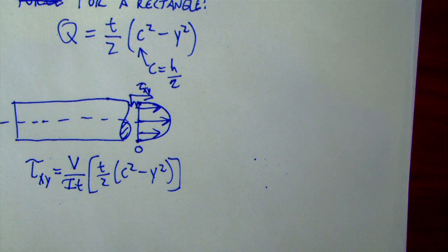So this is cool, but the point here is that we now have to, just like in bending stress, where you have to care about where the normal stress created by bending is at a maximum, now we have to care about where shear stress is at a maximum. And we don't just have to care about the value of shear stress, we have to care about how it combines with the normal stress acting on a given point.